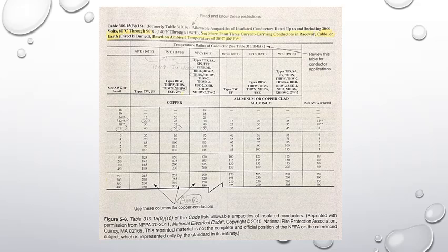Selecting a conductor size. A utility room in a home that you are wiring needs a 20 amp receptacle for the washer and dryer. The conduit will be run from the circuit breaker panel to a box in the utility room without going through the attic. The conduit will be the equipment ground and contain one current carrying conductor, the hot, and one grounded conductor, or the neutral.